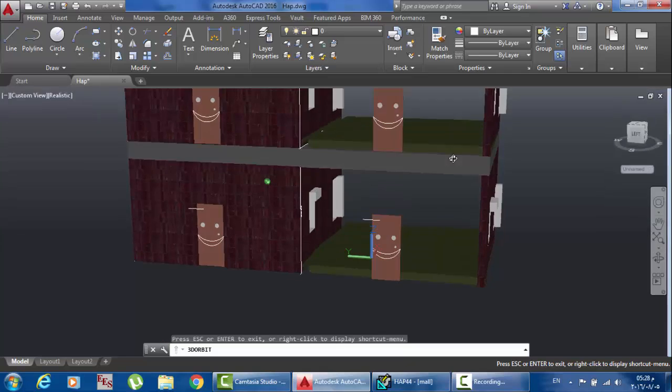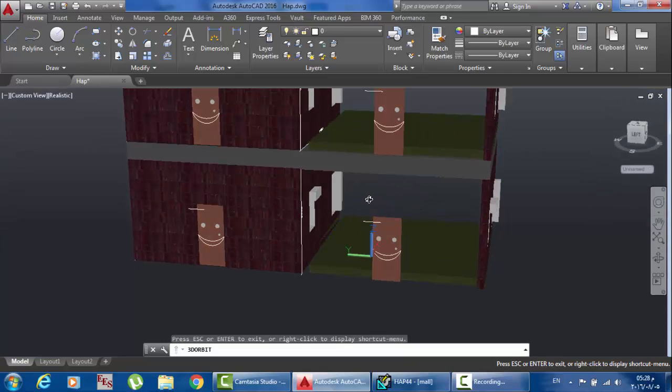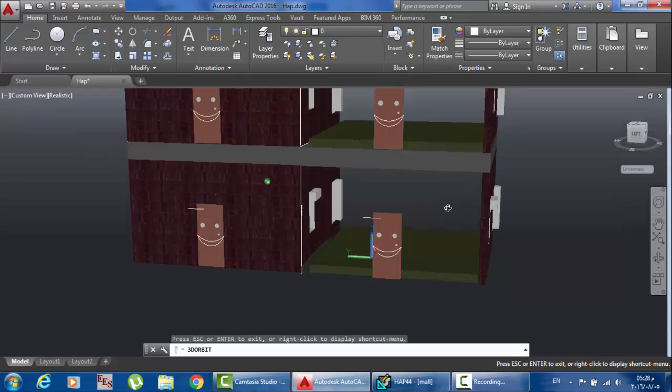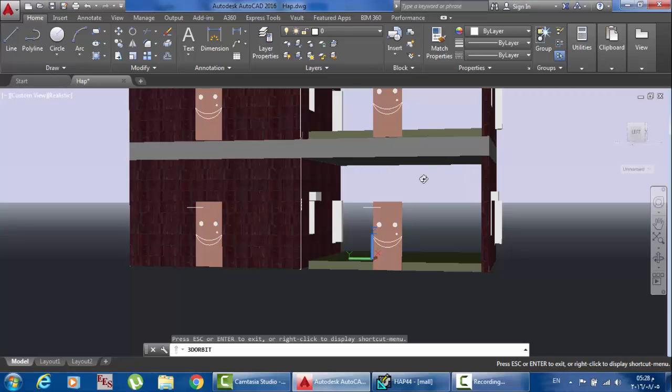Suppose that this zone is under a conditioned zone, so you do not have to define the ceiling, because there is no heat transfer from here to here, because the degrees will be the same, 24 Celsius, and here is 24 Celsius, but this is unconditioned space and unconditioned space, and the heat transfer will occur from the hot place to the cold place.